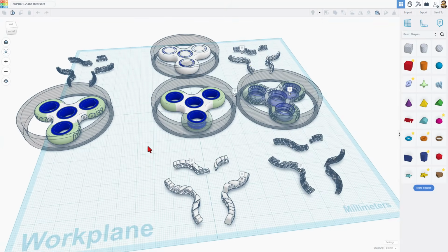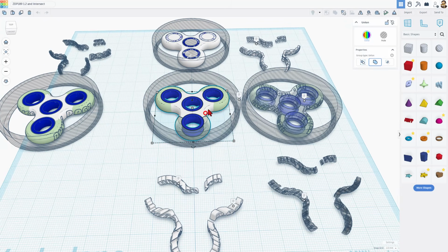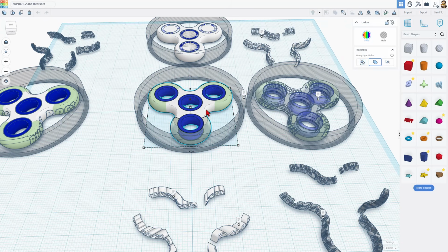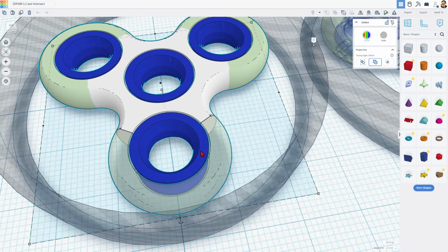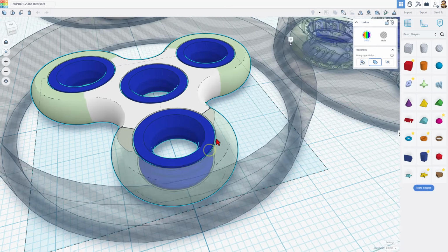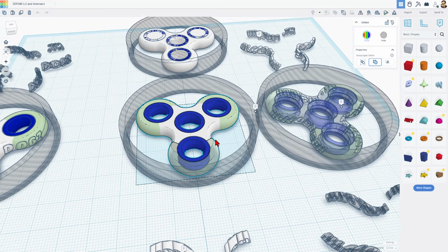All right, so we are back to the Tinkercad project. Let me show you the steps here. Of course, make the fidget. This uses sketch revolve and some cool tricks to line these up. They turn out super slick, and there is a 0.3 or 0.4, depending on how you build it, gap between them. They print in place and work fantastic.